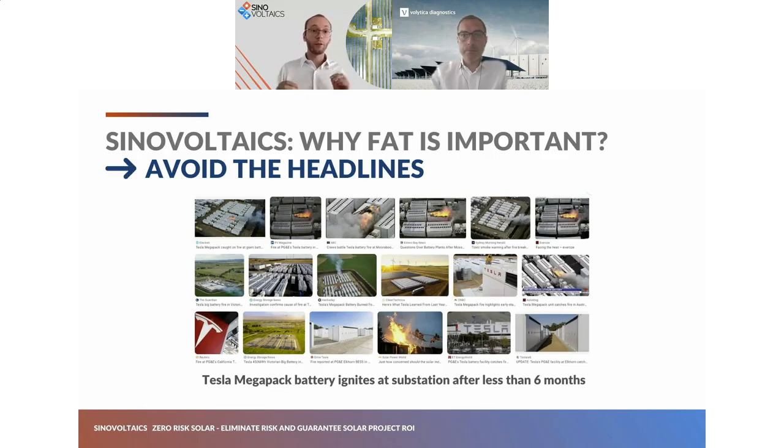First of all, it is to find the critical defects that may generate really bad events later in the life of your BSS. The ones that come to mind are battery fires that will last for several days. And unfortunately today, as soon as you have a fire, including lithium-ion batteries, your name will be all over the news. So this is the first reason why you want to do a FAT: to check those critical points.